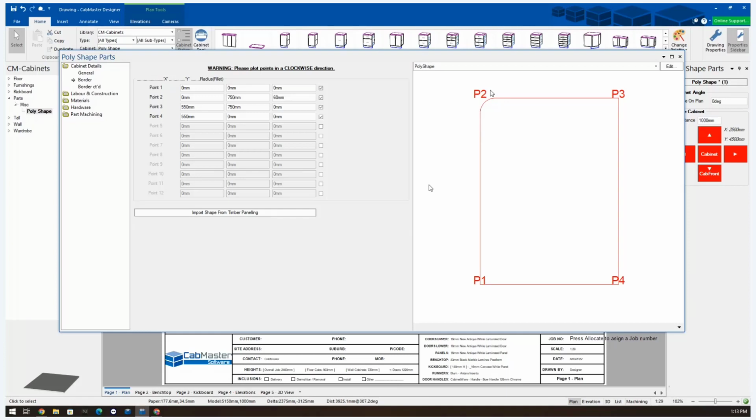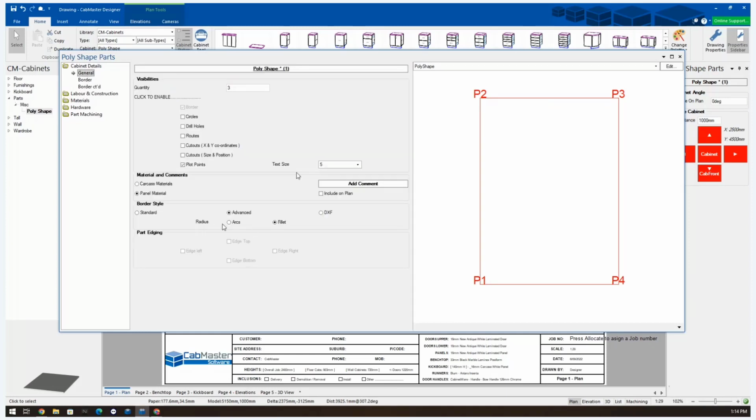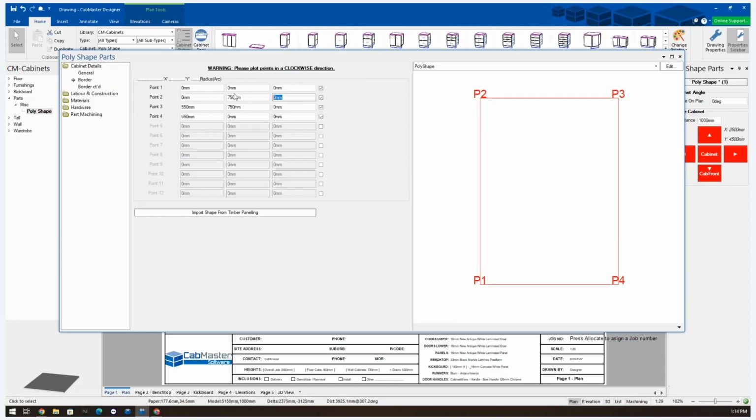This basically allows you to create a curved edge to the plate. If you put in a minus figure here, you'll get an inversion. This also occurs when I go to arcs. If I put a minus figure in, say minus 400, it will invert. Now you might be wondering why I put 60 for the other one and 400 here, because I need to have it in relation to this. If I put something small here, you'll get a weird, this is how much your radius is.